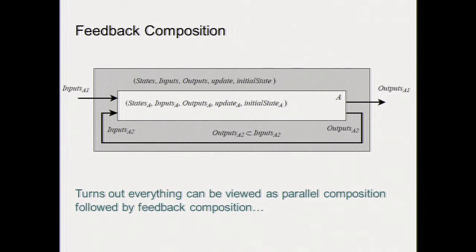Now, I know that you already seen, yes? No, because we are talking in the domain of finite state machines. So a finite state machine intrinsically is never time triggered. And then it's a single system, right? So it doesn't make much sense to be time triggered. When you have two things, then you can say time triggered or event driven. But if you have a single thing, it's the same thing, time triggered or event driven, right? Because it's a reactive model. Okay, so I put an input, something happens, and then, okay.